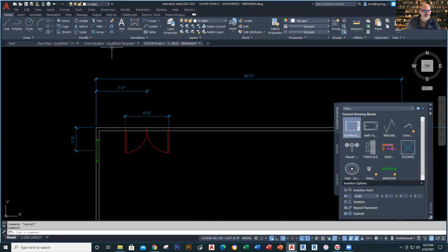Okay, walls. So I'm going to go ahead and start. I'm just going to make this a line. So I'm going to touch it here, and I didn't click. 5'8", and then 2 feet, and then 4'8", like that. And I pull this down in this direction, and I snap it right to there. And when I do that, boom, it gives me that right there.